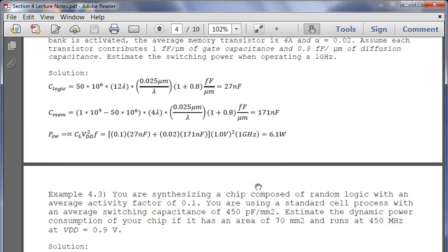Yeah. And here's the thing, if we recall from the first day of lecture, we're going to recall that our feature size is going down, which means our lambda, which is feature size divided by 2, is going down. As our transistor size is going down, we have the same amount of area, so we're just going to put in more transistors. That's why we have this transistor graph that pretty much went like this. So we're taking advantage of that same area with smaller sizes.